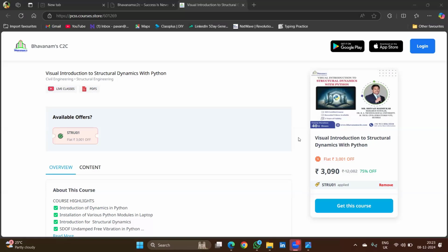At this earthquake magnitude, what is the performance? There are levels, if you have studied this: immediate occupancy, life safety, collapse prevention. All these levels are based on certain magnitudes of strains in the structural elements. In the initial video I showed you from Perform 3D, there was color coding, the red, yellow and green colors. These are the occupancy levels. That is how you achieve performance, and then you convey that this is the performance of our building. Okay, sir.